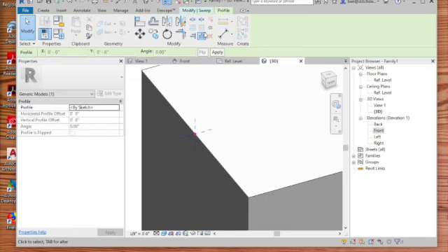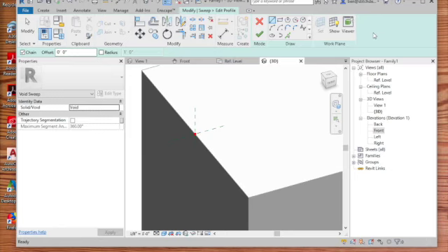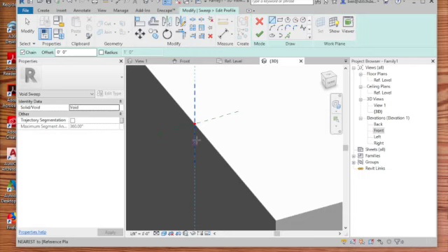Let's go back up to our taskbar and select Modify Sweep. In the Sweep tools, we're going to select Edit Profile. This will allow us to custom draw any profile that we want taken away on the path of that sweep. Now, starting from the center point of the XY axis on the interior of the cube, we're going to draw a 6" by 6" square.